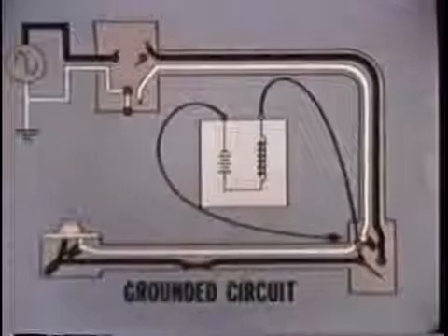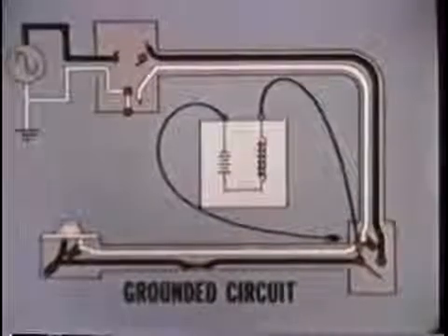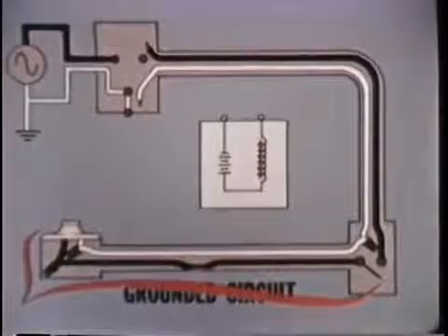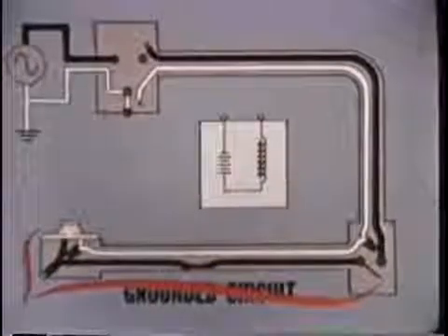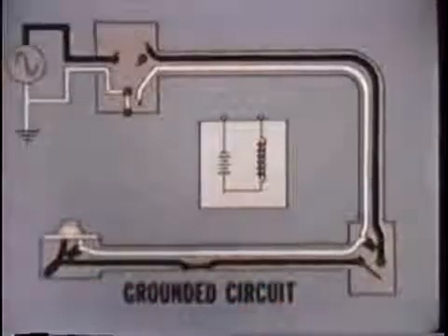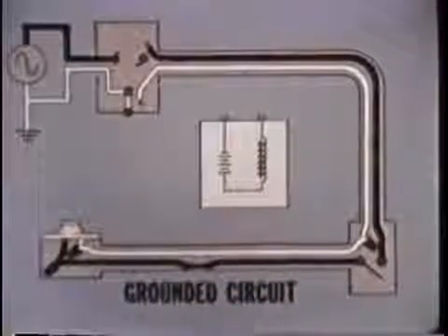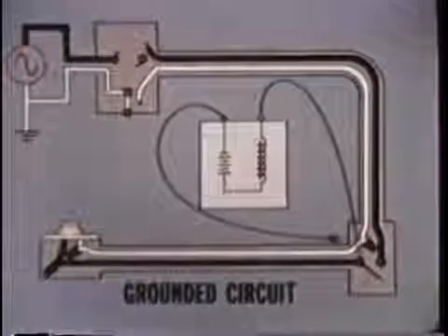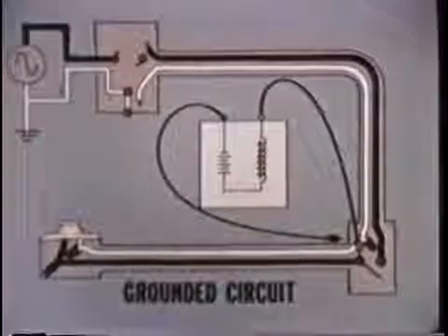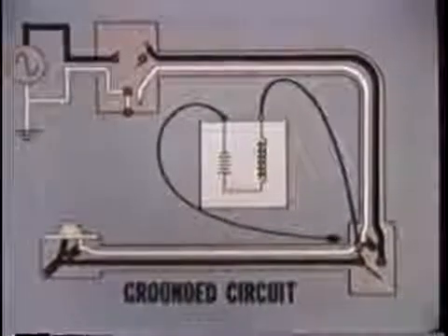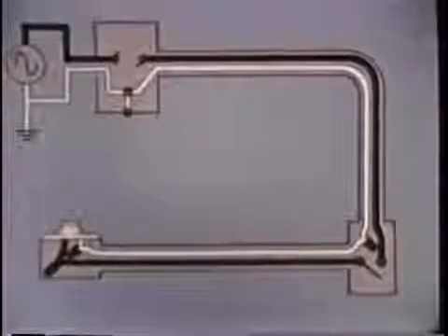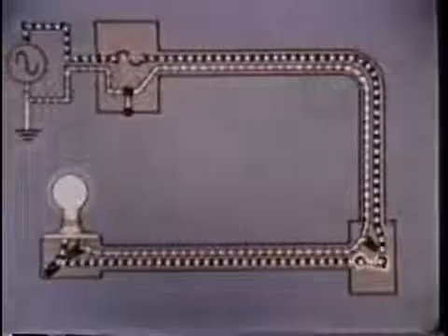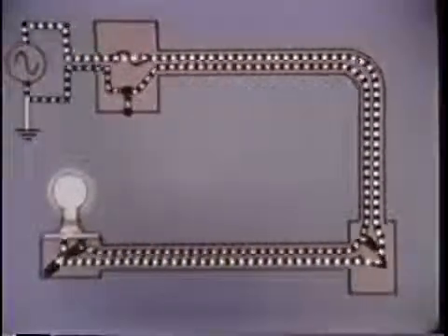However, between the hot conductor and ground in the second section, there is continuity. Since this is the last section, the testing is complete. In a longer circuit, the diagnosis would be confirmed by checking the next connection. The ground is removed, and the circuit is retested at the trouble point, and all connections are restored. The light and fuse are replaced, and when the switch is turned on, the circuit is back in service.